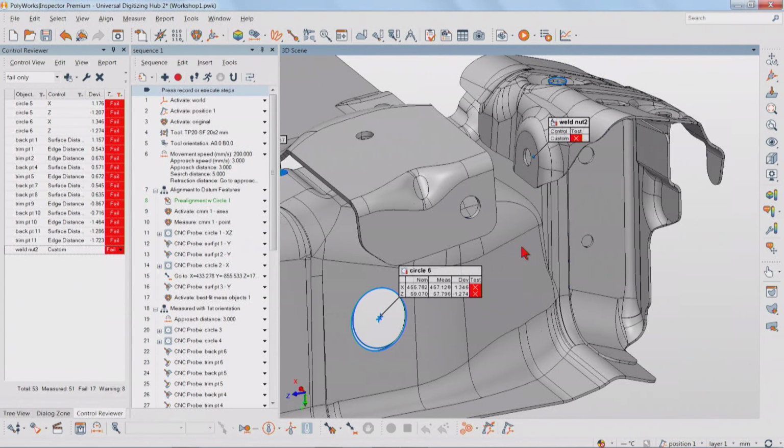So I'm looking at this, and again, I'm thinking, okay, the part's still on a CNC CMM table. I could inspect that using the probe, and I could probe several surface comparison points. First thing is that's going to be time consuming. Second thing is there might be some collision. Maybe the part is not located in an ideal manner to quickly measure those. And ultimately, we would all know that this sounds like a job for a laser scanner. Now, it's great if you have a laser scanner for your CNC CMM, but the model I'm using right now doesn't.